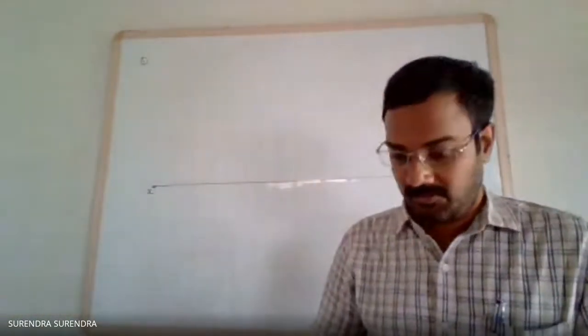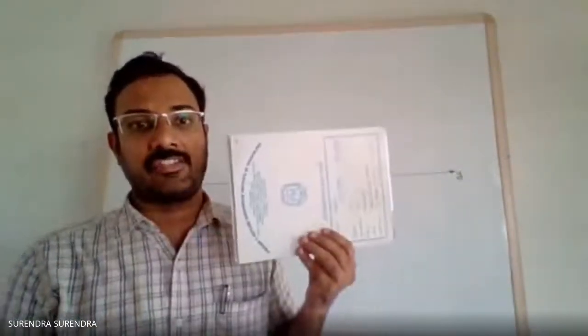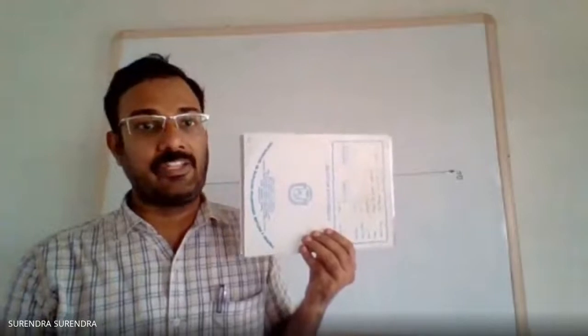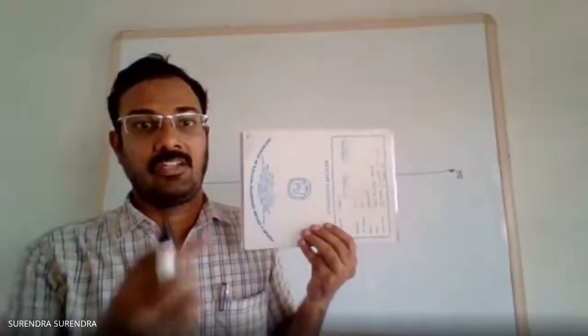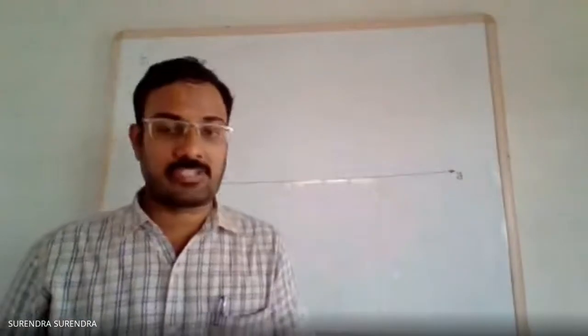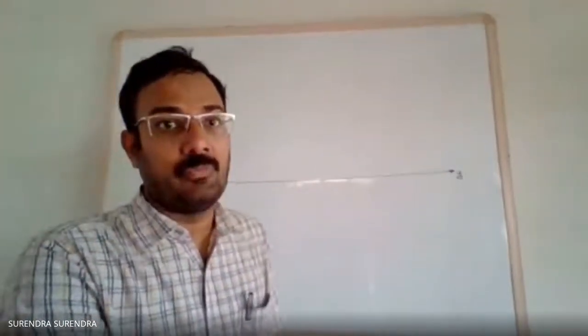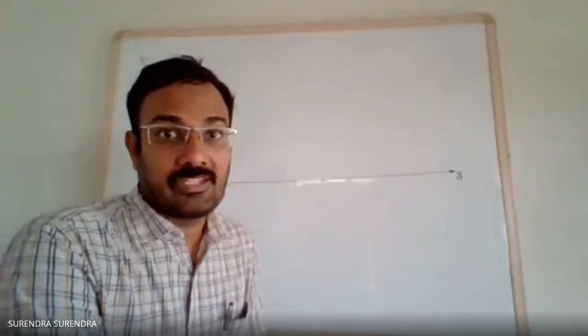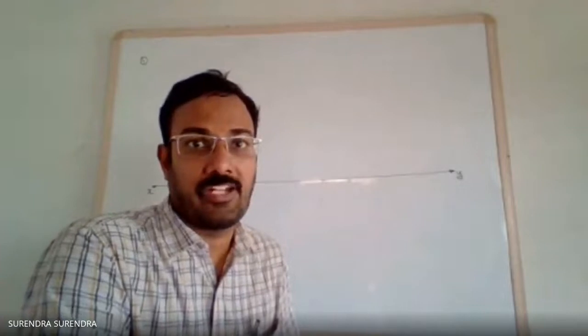In all three cases, the surface is parallel to the vertical plane, so you can see the true shape of the surface in the front view. So we must start the problem with the front view. We always start the problem in the view where the true shape is seen. So for this problem, we must start with the front view.